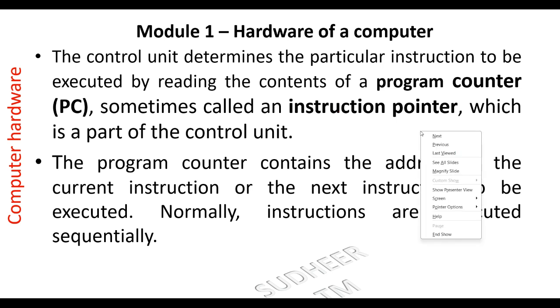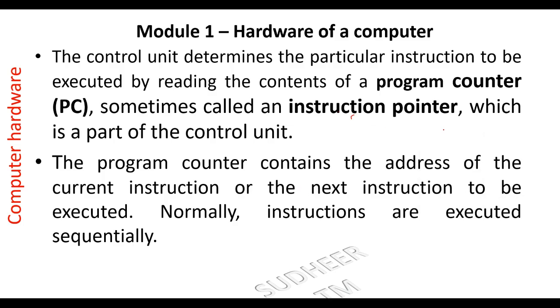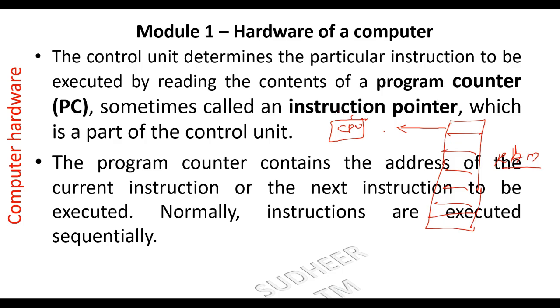While an instruction is being executed, the processor needs to get the next instruction from the memory. All our software is loaded into internal RAM memory. We call it primary memory. From the primary memory, the microprocessor CPU or controller CPU will read one at a time. Sequentially, each instruction will move into the CPU. We have seen how this movement works. For that, our processor has one special register. We call that register the program counter.